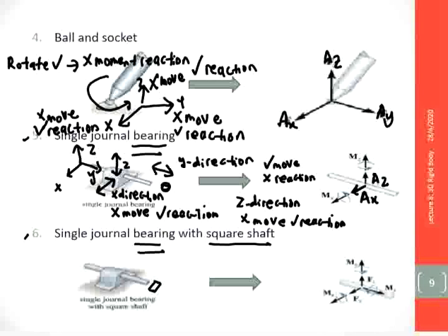We already considered the force reactions, and then we need to consider the moments. In the x direction, this shaft can move freely, which means it can rotate clockwise and counterclockwise. So there is no moment reaction.